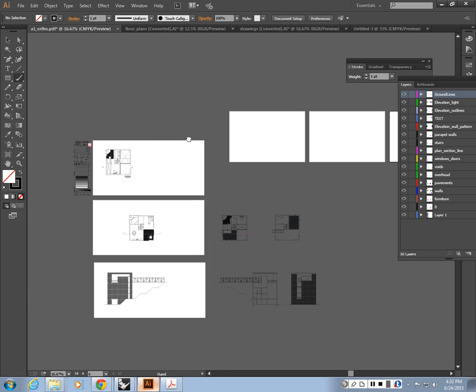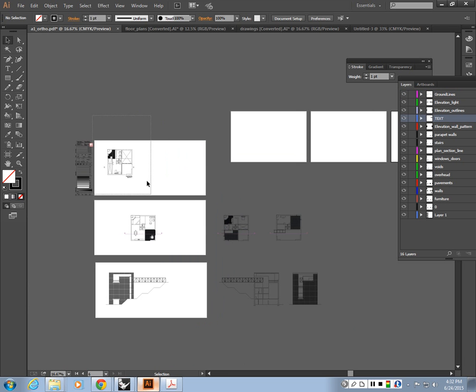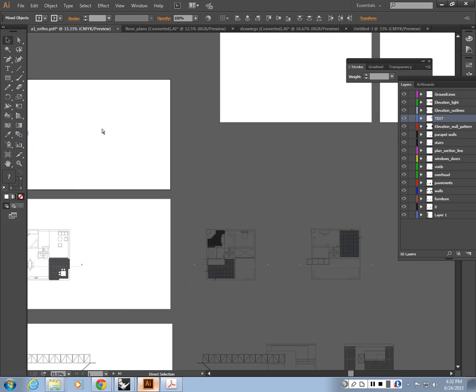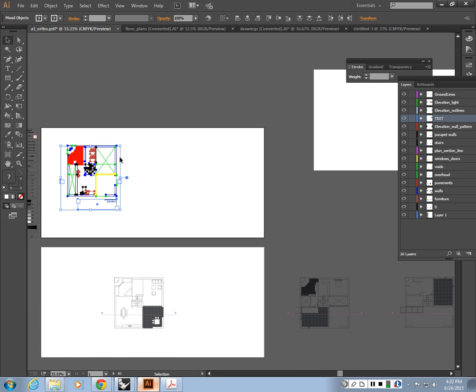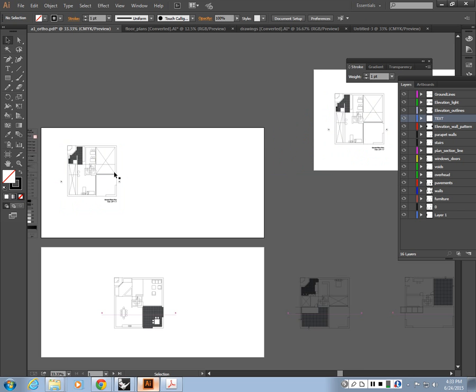And then if you want to copy your floor plan, choose your floor plan. Look at my cursor. It's switching from arrow to arrowhead, something like that. Do you guys see that? It's doing that when it's over geometry. If you want to copy the drawing, you need to be over the geometry. And then when you press Alt, you will see the double arrow. And then that's basically how you could copy it. So I can come in here, and then drag. That will make an exact copy of it.